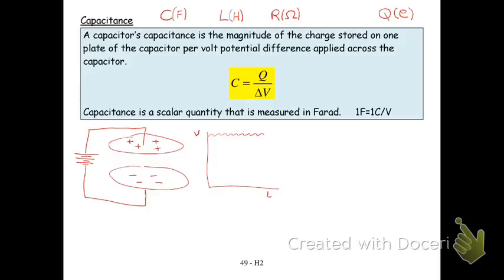If I just amplify it, I have a huge problem, because to get the signal big, it gets a very big voltage. If I make this a factor of 2 higher, then this is 2 times higher too. It's a real pain. So what I can do is put this through a capacitor. It will get rid of all that DC, so you end up with the same small signal without a background. Then I can amplify it 10 times and I get a much bigger signal. So it's great for that.